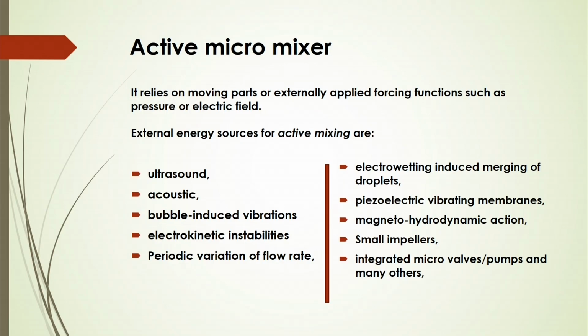That external energy, what should it be? That may come from an ultrasound source, that may be acoustic, that may be bubble induced vibrations, that may be electrokinetic instabilities, that may be periodic variation of the flow rate, that may be small impellers or micro impellers, you can say, and that may be magnetohydrodynamic action, that may be due to piezoelectric vibrating membranes, that may be electrowetting induced merging of droplets.